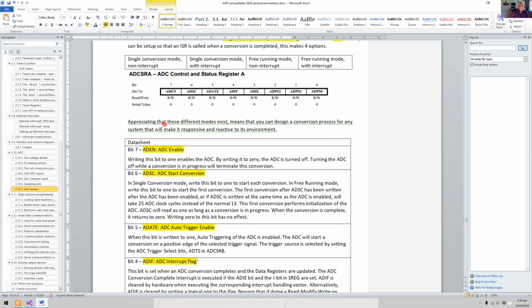So let's have a look at some of the values in this ADCSRA register. ADEN, okay, so ADEN is our enable. Now we don't want to waste energy nowadays. We're right into maximizing the use of these microcontrollers. If we waste a tiny bit of energy, then we multiply that by millions and millions, because that's how many of our circuits are produced out there, okay? We want to avoid this. We want to increase the energy star rating of our devices.